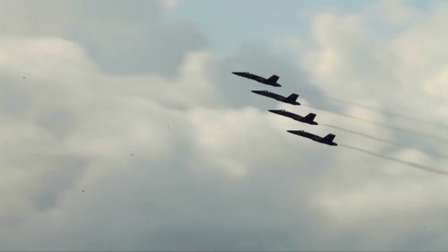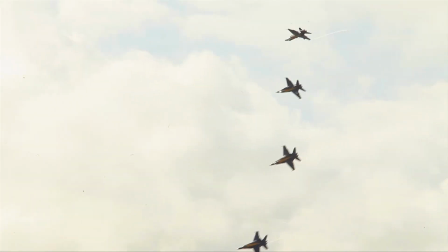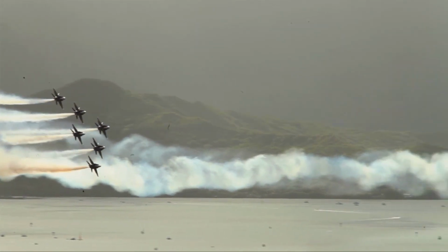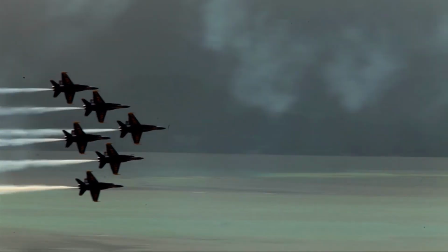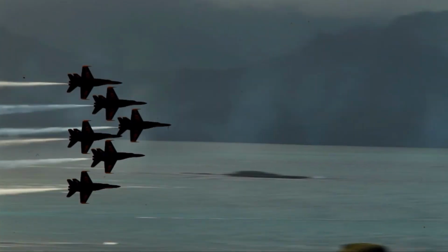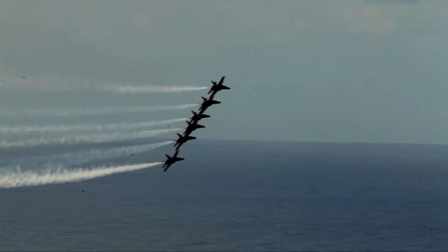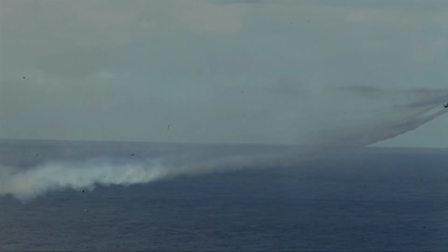The elevator, the rudder, the aileron, these are all called primary control surfaces. Let it be any type of aircraft, these three control surfaces will be there. Now we will see some additional control surfaces which are called secondary control surfaces. These enhance the performance of the aircraft. Though not all, most aircraft have these control surfaces too. These are flap, air brake, spoiler, etc.